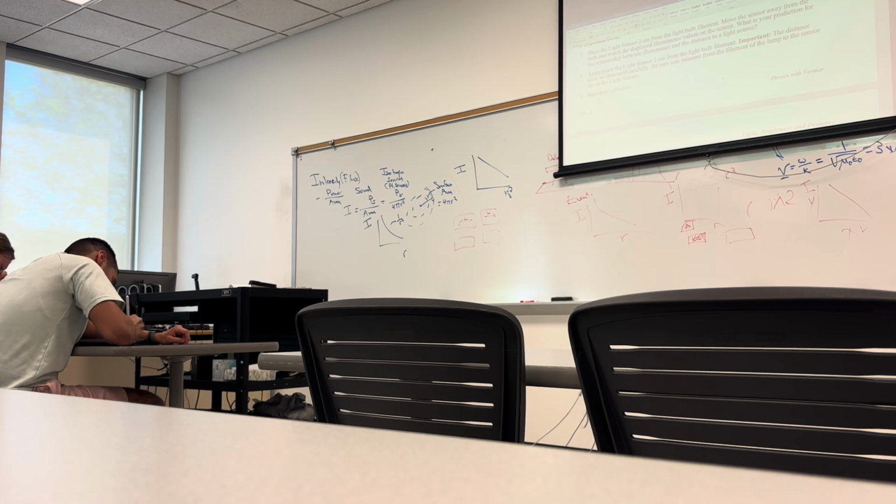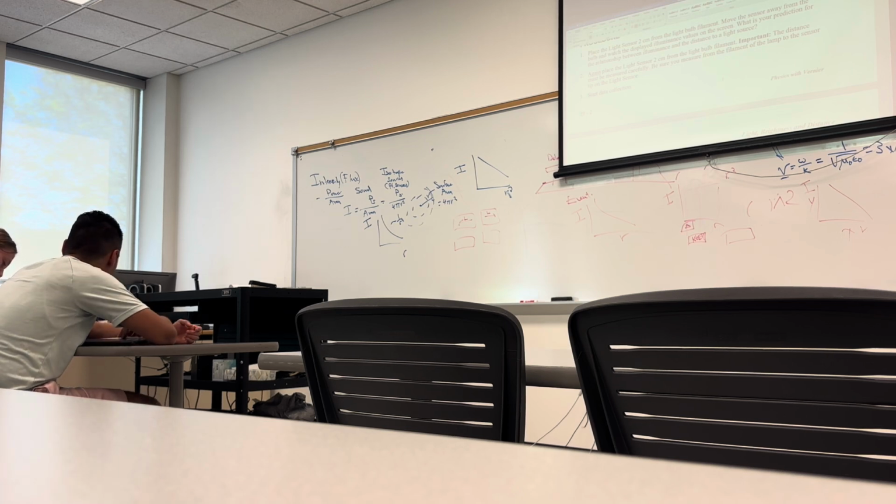So some people zero it then and hope the room conditions don't change. So even though it normally says cover it, what I recommend is you don't cover it. You get everybody, all the room lights are down, nobody has their own individual light switched on. The background light is the way it's going to be. Keep your own laptops and stuff away. And zero the detector then.